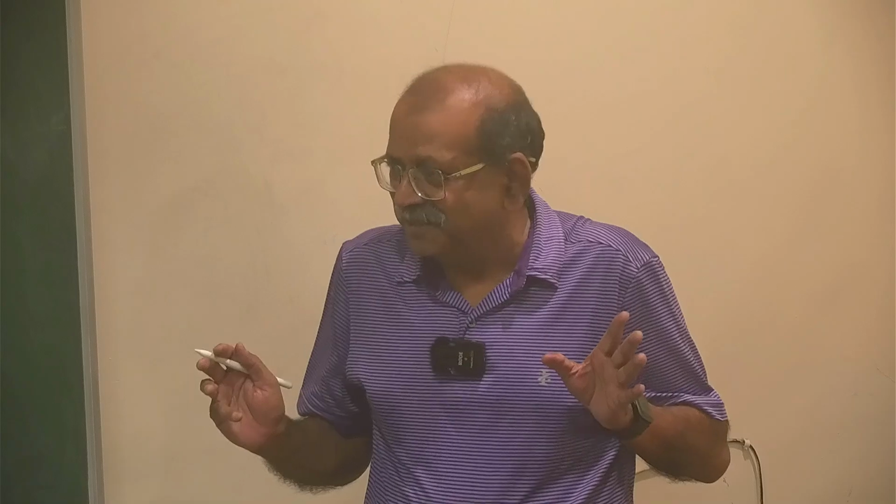So dimensionally nu t will be equal to K square divided by epsilon. But when you write the model equation, you always say nu t is equal to C mu times K square upon epsilon. And this C mu is the dimensionless constant which you put, and the only way to get C mu is experimental data. You will not be able to derive this dimensionless constant from dimensional analysis. It will only come from empirical data.